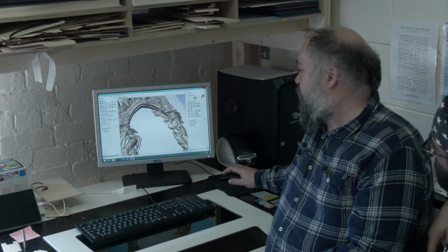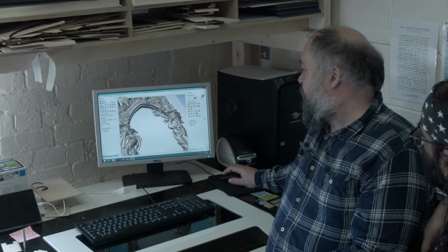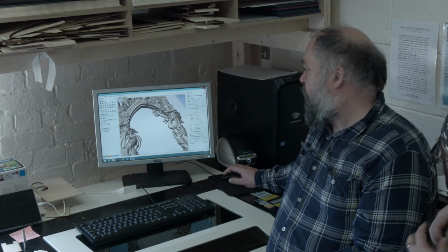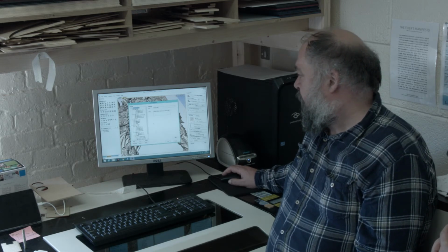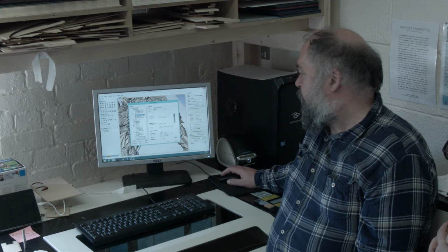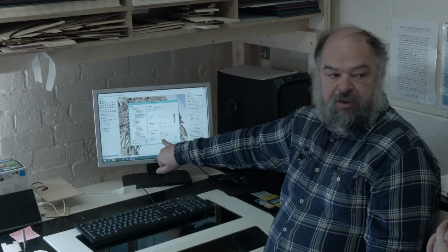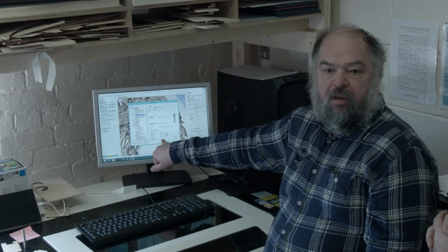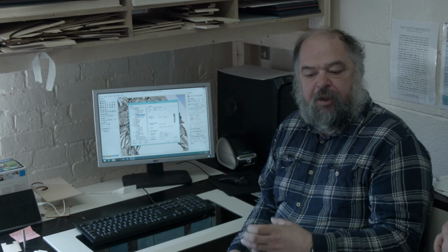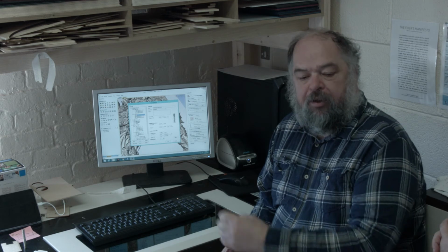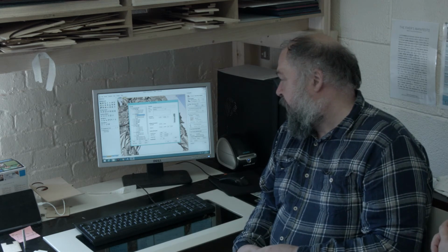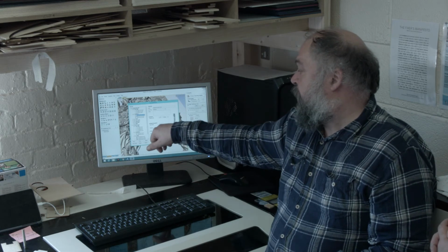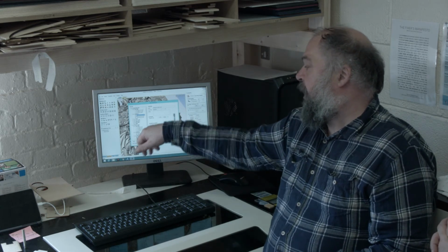What happens in the tool here? If you go into one of these in the tool library, each tool has a tool number, so that's tool number 1. So the next tool will have tool number 2. So an automatic tool changer will go, right, at this point I need to go and grab that tool, at that point I need to go and grab that tool, and it changes it that way. So it knows from off there. And they say all your speeds and feeds and how much step over, pass depth, etc. is all coded within this.